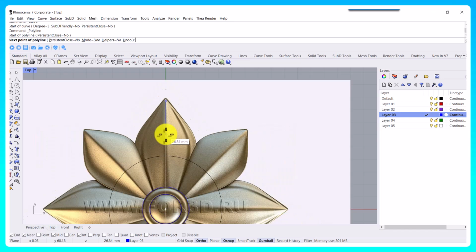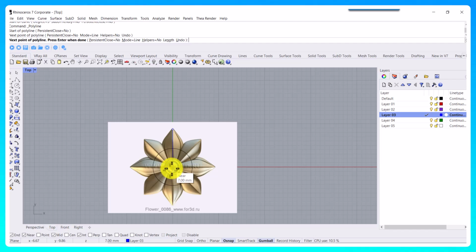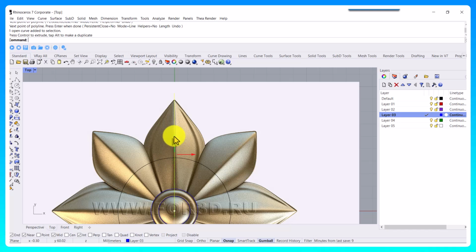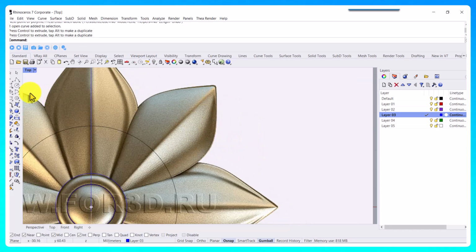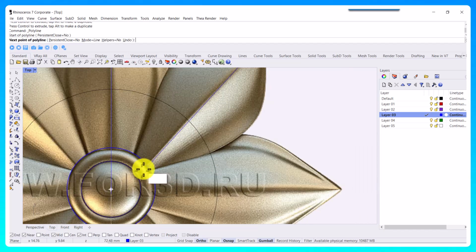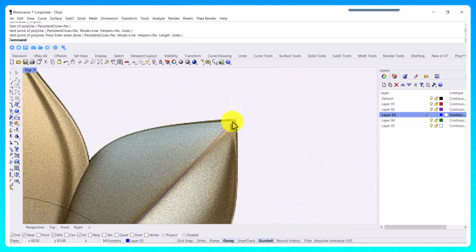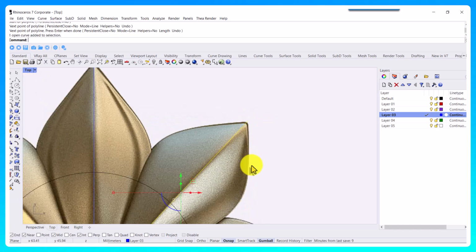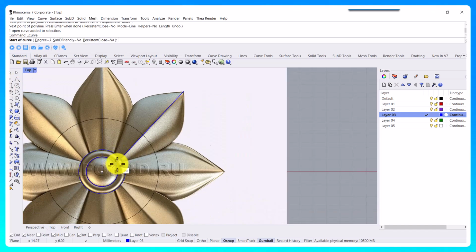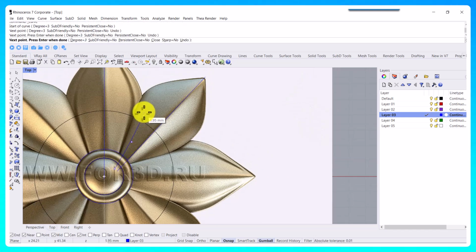So before that, for mirroring, I need a center line, so I choose this line to be as the center line for mirroring, and again here I need the center line for mirroring command, and I think it is good. Now I choose the control points curve and start drawing curves over the edges of my model.